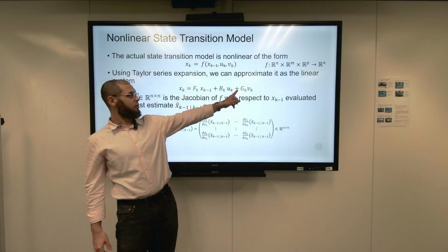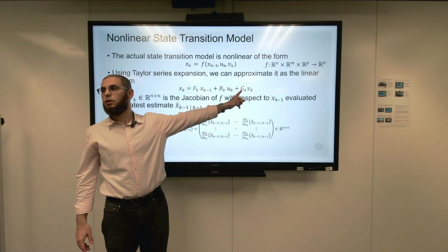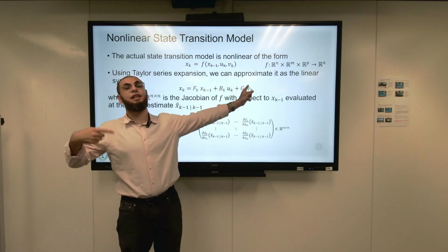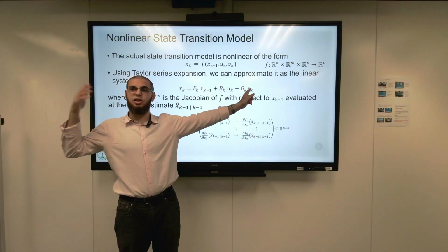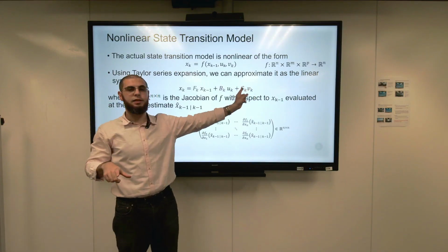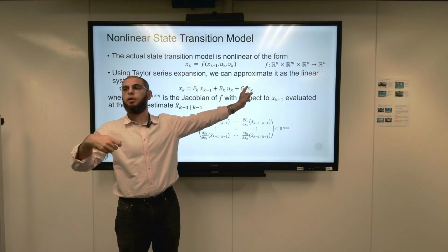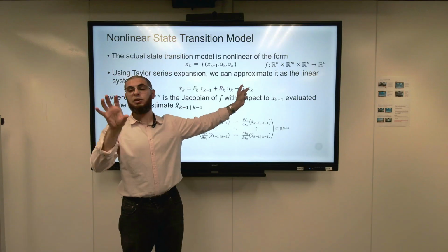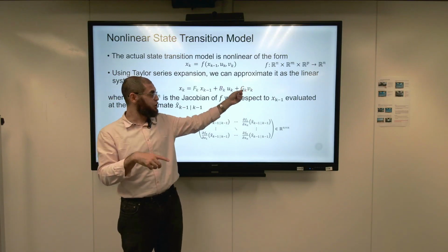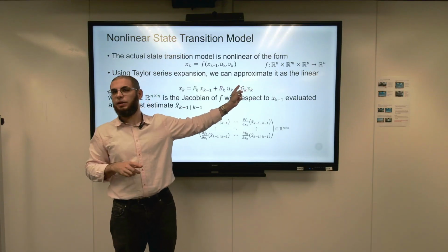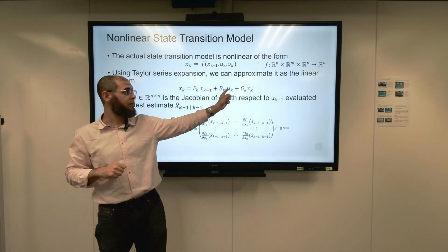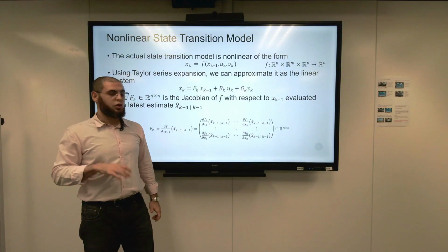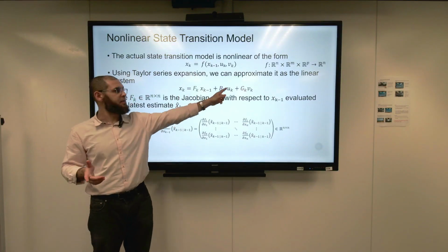This is something that we're seeing here for the first time. It's because the noise actually can appear non-linearly. Earlier, we just assumed that the noise was just some additive noise. We always assumed it's just some number and we can use it. But here, it usually has some corresponding matrix that you use. And the G will appear, it will change a little bit the equations of the Kalman filter. Okay? So the only thing is how can we calculate the f, the b, and the g?